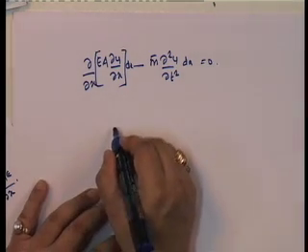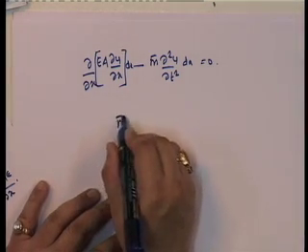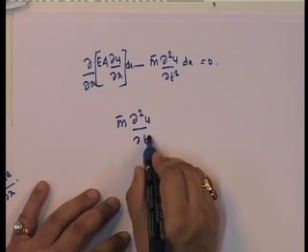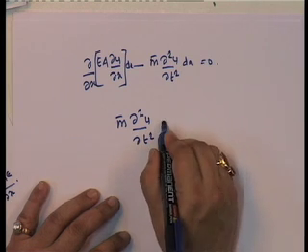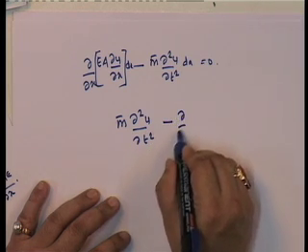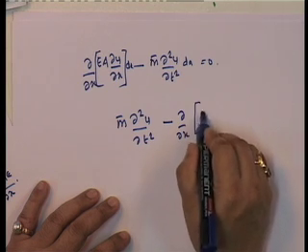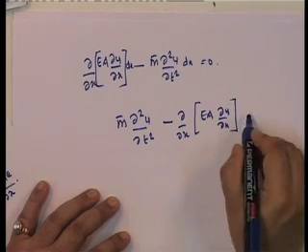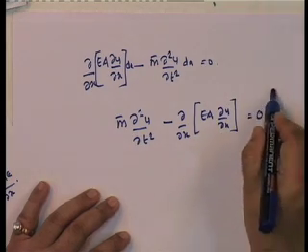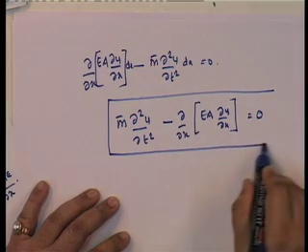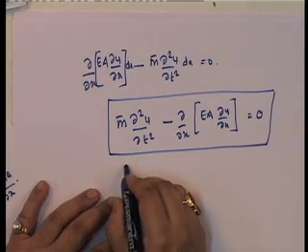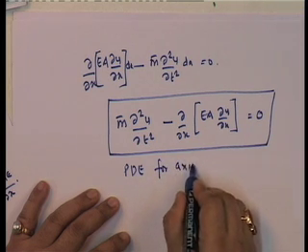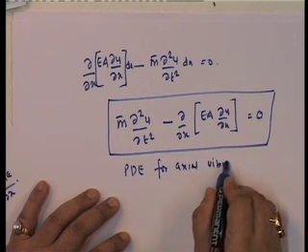So we can write this equation in the following format: m del squared u by del t squared minus del by del x of E A del u by del x equals 0. So this becomes the partial differential equation for axial vibrations.